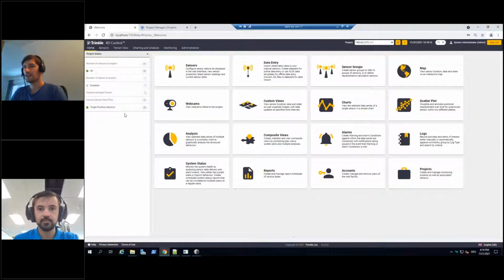Okay, perfect. All right, so let me explain how you can get to the alignment-based values. So maybe first some explanation on my setup. I use a real alignment that has been used, or that is still being used, by the Grand Paris Metro project. You will also see it later on the maps page. I have configured about 40 positional sensors, prisms basically, that are close to the alignment and for which I get data from on a regular basis. This is all configured already in T40 server, and therefore I will start in T40 web right away.